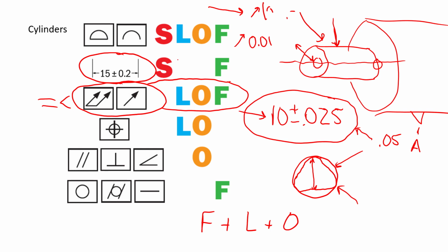However, if we get to a point where we had the example before, where we had the 0.1, so now the runout tolerance is twice as large as the size tolerance. Well, now the size tolerance is what is picking up that limit to the form, and no longer is runout capturing that. It's really acting as a position tolerance.